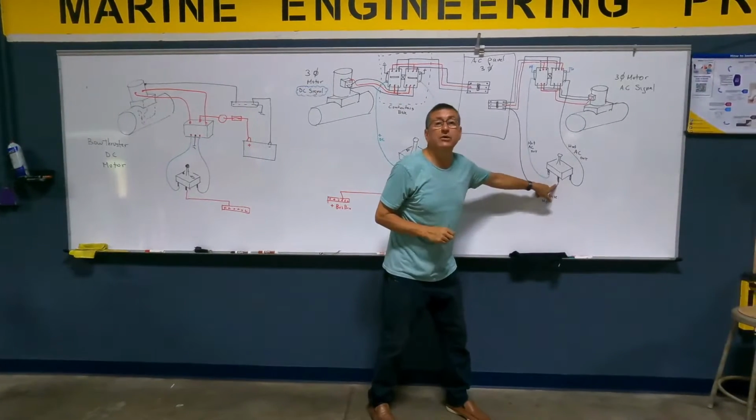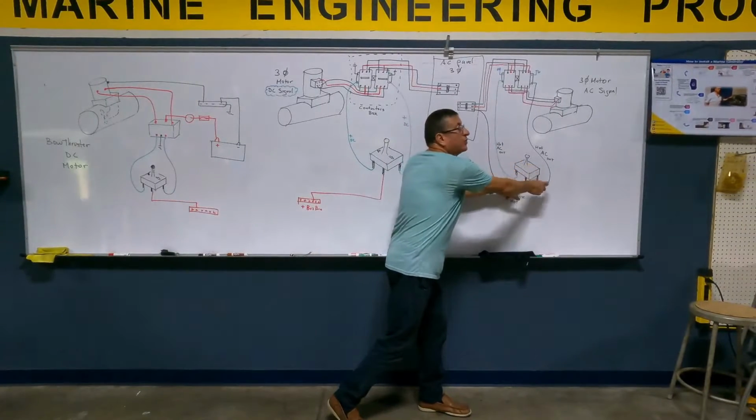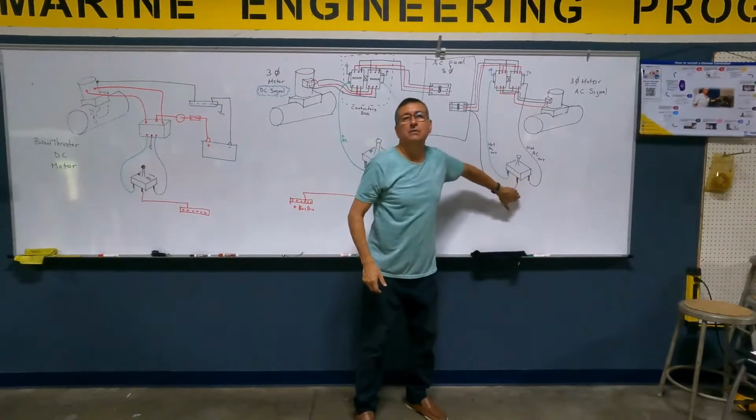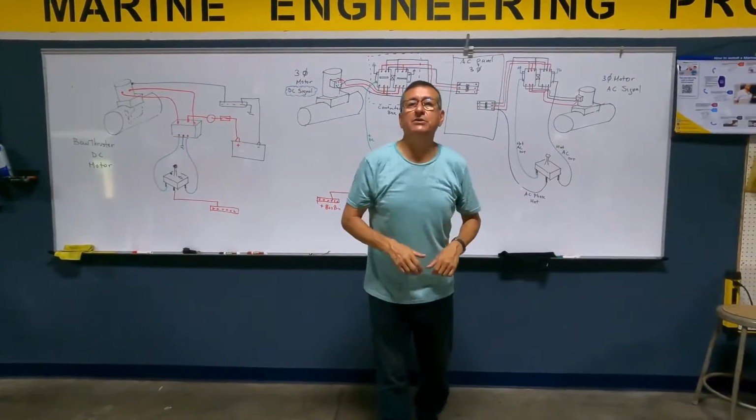Okay, I have power in the middle. Let me move it here. I have signal. Let me move it here. I don't have signal here. What happened? Either the joystick is damaged or the switch is damaged.